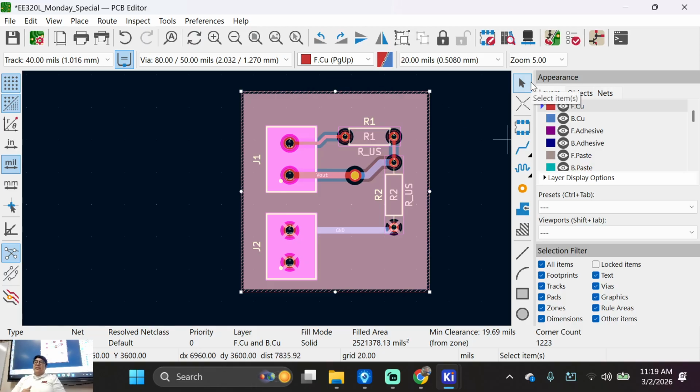Okay? When you add a copper plate too, you also reduce the manufacturing time as well. Okay? So they're not going to add copper. They're not adding copper. They give you a default copper plate and they're etching copper. Okay? So you're actually making their job a lot easier by doing these types of planes. Okay? Does that make sense with everybody? So they don't tell you this, but it makes their job easier and then they can print the next student's board, all right?